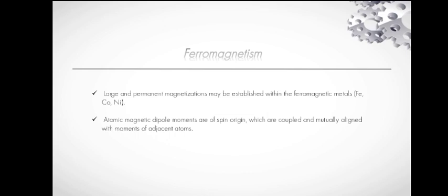In short, the permanent magnetic moment in ferromagnetic materials results from atomic magnetic moments due to the uncancelled electron spin as a consequence of electron structure. There is also an orbital magnetic moment contribution that is small in comparison to the spin moment. Furthermore, remember that in a ferromagnetic material, coupling interactions cause net spin magnetic moments of adjacent atoms to align with one another, even in the absence of an external field.